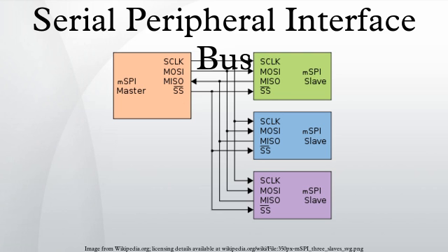Such a ready or enable signal is often active-low, and needs to be enabled at key points such as after commands or between words. Without such a signal, data transfer rates may need to be slowed down significantly, or protocols may need to have dummy bytes inserted, to accommodate the worst case for the slave response time. Examples include initiating an ADC conversion, addressing the right page of flash memory, and processing enough of a command that device firmware can load the first word of the response.